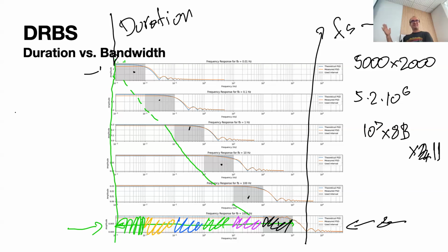Okay, so that is why we are seemingly complicating it like this, and that's why we say that the useful bandwidth, if the bandwidth of the signal is FB, is down to FB divided by 10. That's it. The optimal value would be FB divided by 14. But 14 is a strange number. Let's do it by 10. We are a little bit suboptimal, but who cares? We saved almost 99.99% of memory anyway. So that's why we do it like this. Okay.